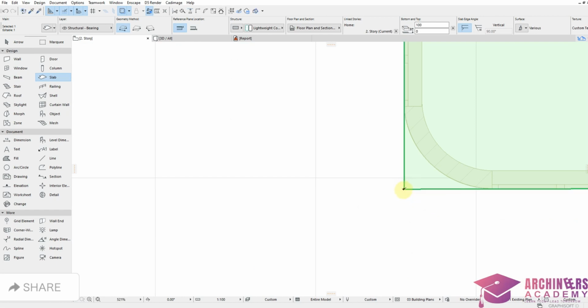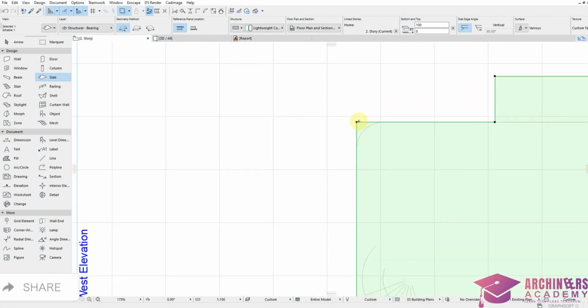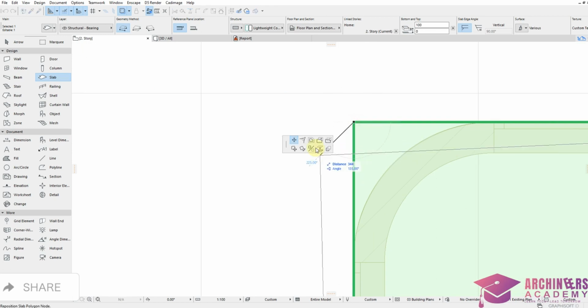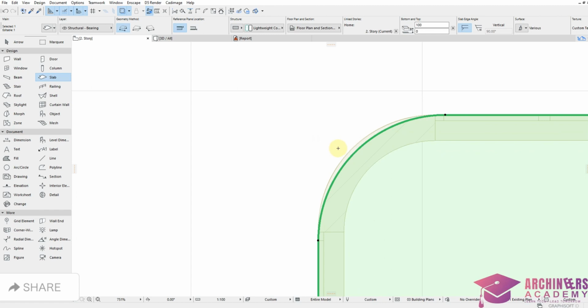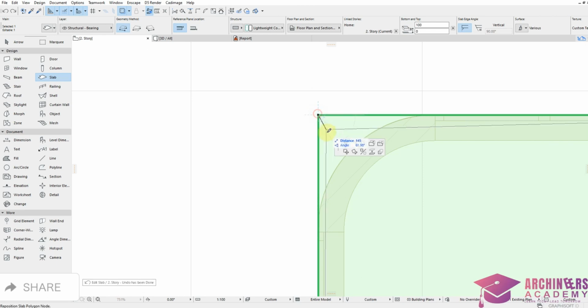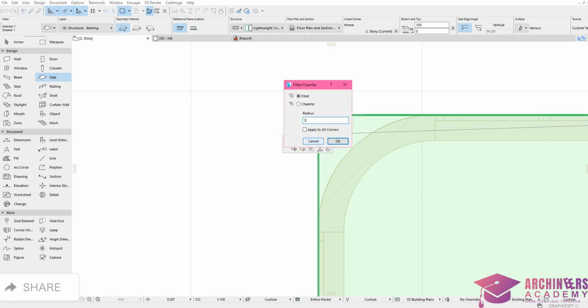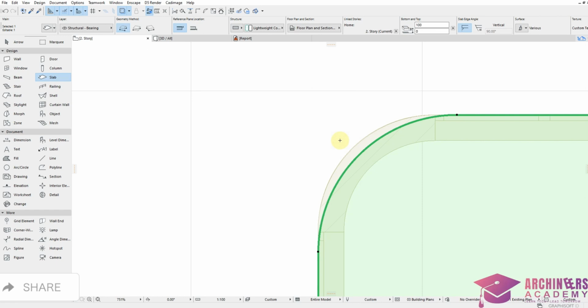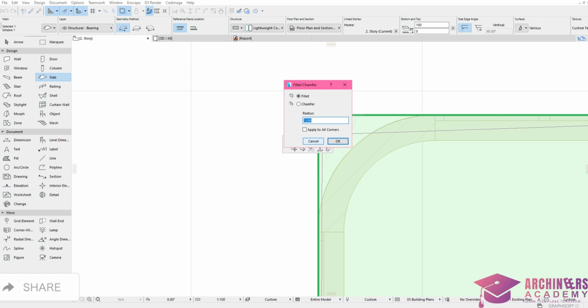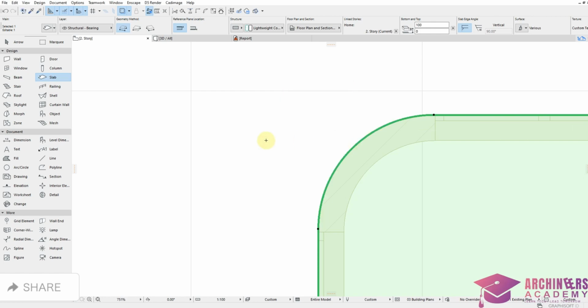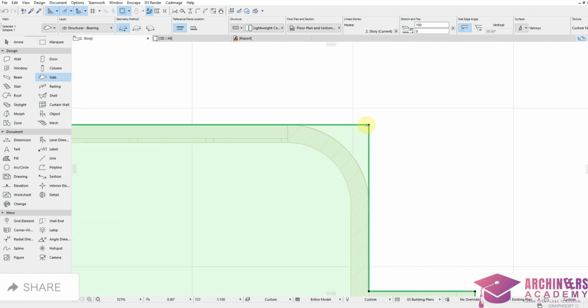Just pick the black bullet, go over to fillet, 1, okay, just the same thing. Move to the next one, pick on this one, okay. This particular one at the back is a bit smaller, so I have to adjust this to 1, 2, okay, adjust this to 1000. I just checked that it's lapping at 1000, so that means this one too will be 1000.